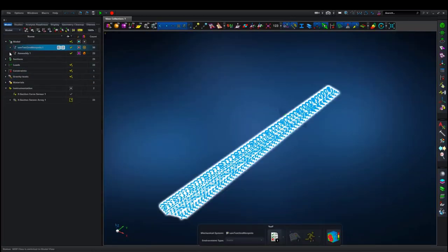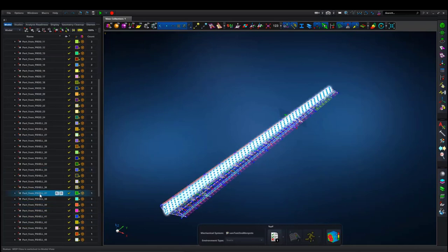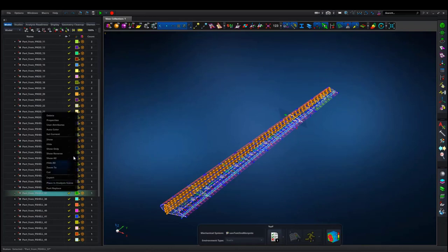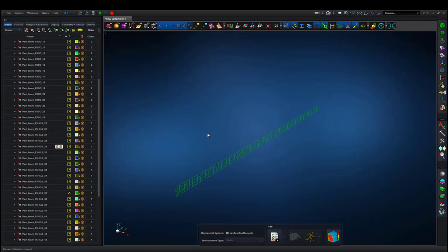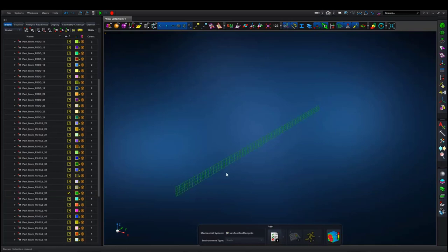Let's say we want to look at the load distribution, not along the whole wing, but instead along the entire length of one section of our model here. In this case, the wing spar. If you're using anything other than MSC Apex, this would require rerunning your model and possibly even remeshing your wing spar also, since the location you're interested in probably has to line up with a node on the mesh. Not so here within Apex.